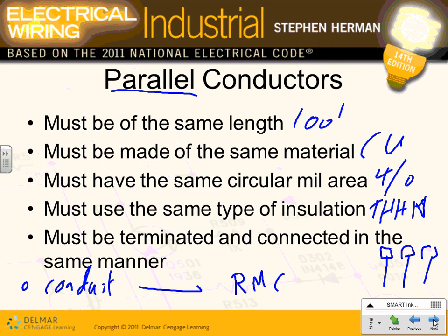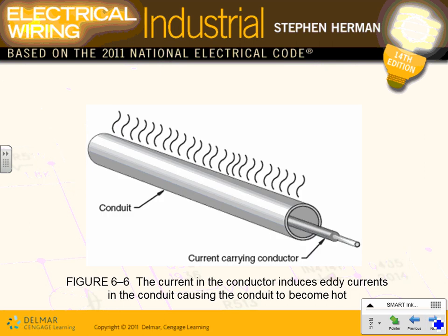Any comments, any questions? Let's review for all of you, right? It makes a big deal, guys, when we do takeoff, next section. So when you do your equipment, if you don't do that, Jeffrey, right? If you put one phase A in one steel conduit, you created an inductive heater, right? It will induce heat, it's like a transformer. It will induce voltage here, and that in turn will induce current here. And long story short, the conduit will be hot.